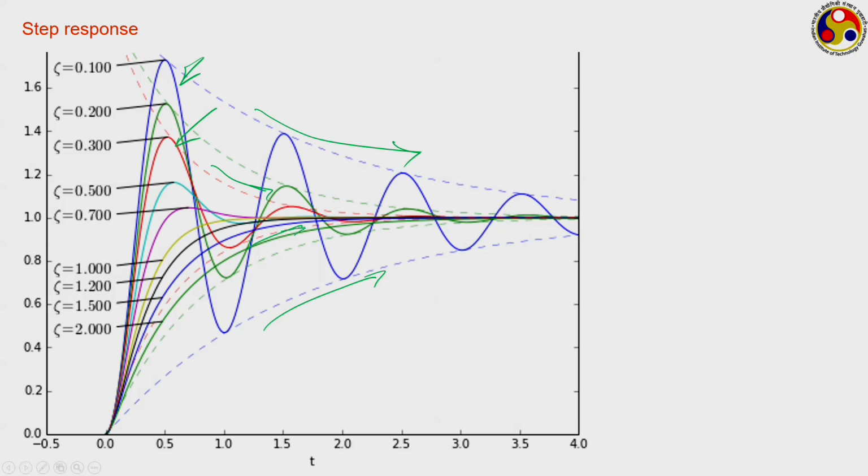You can see that it is continuously coming down, and it is trying to settle down within a reasonable range much quicker. When zeta equals 1, it just follows this particular curve, it keeps on increasing, and there is no oscillation at all; rather, it follows that one value quite quickly. So, as the value of zeta increases, the oscillations get dampened, but also the time required to attain the value of 1 for the first time keeps on decreasing.